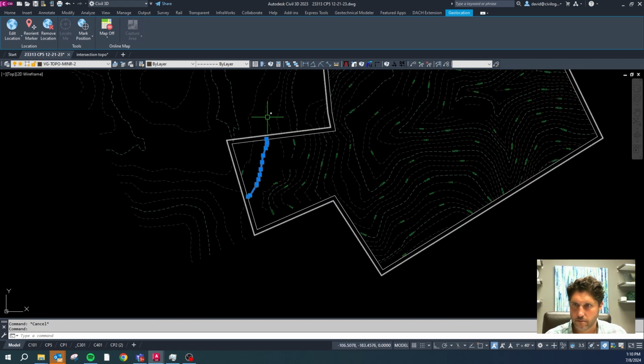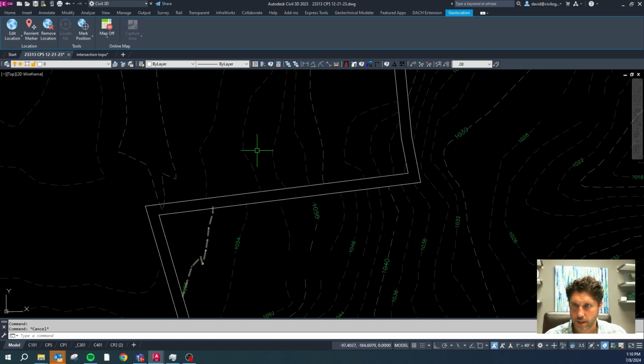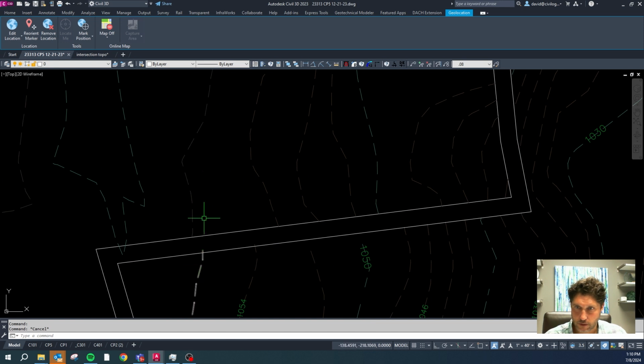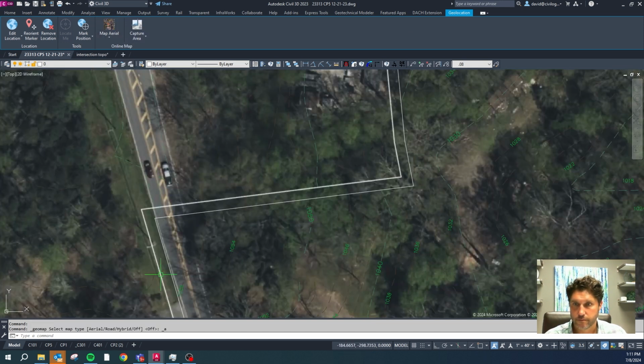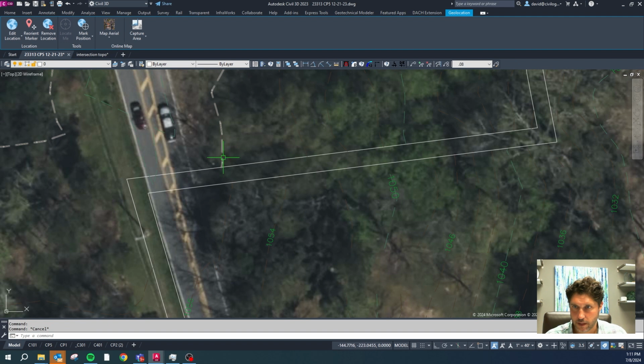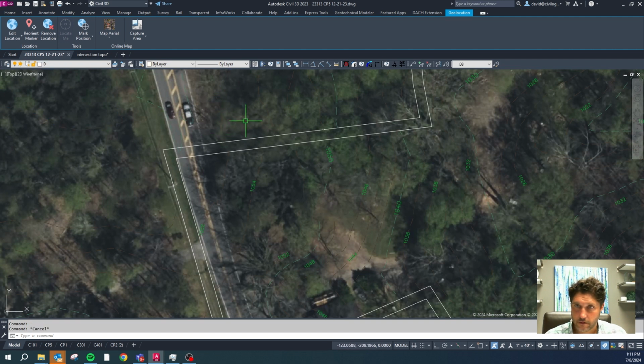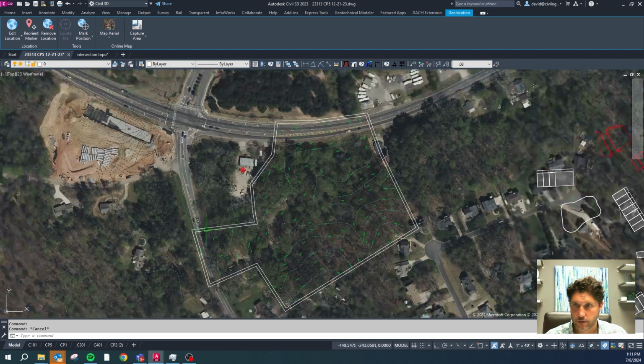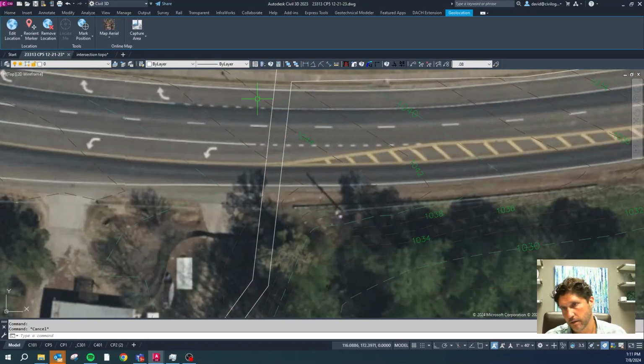based on this topo being in the roadway. So if this goes this way, if this topo is 56, and this one's almost in the same place. Let's turn on the road so we can see this. And actually that's not in the roadway. It would have been nicer if we were matching up in the roadway. If that one's 56 and this one is 58, we can tell that the GIS topo is about 2 feet different. Let's see how it looks here. Oh yeah, this is a good example.